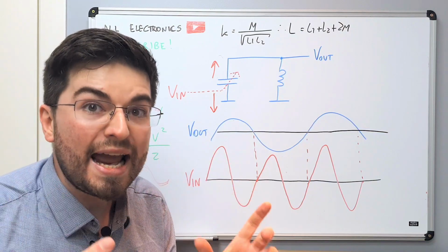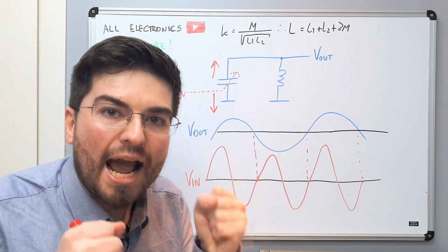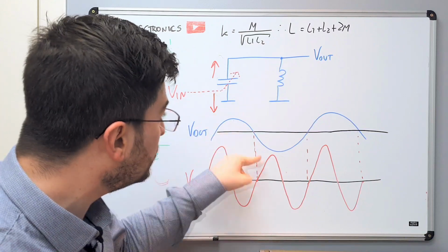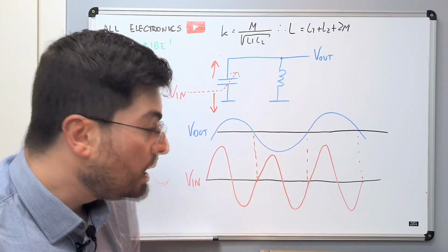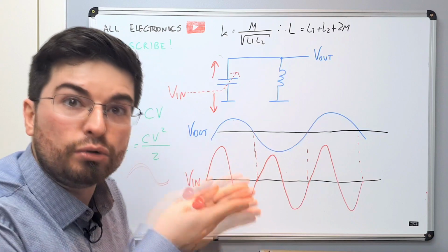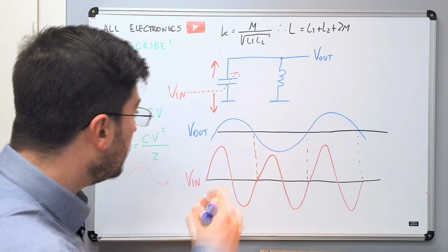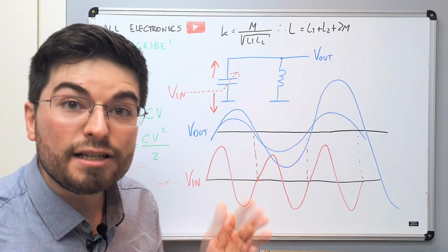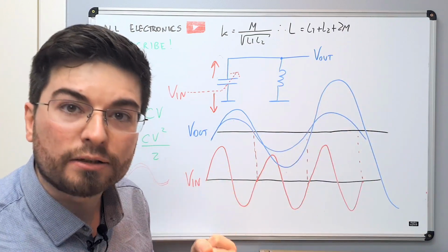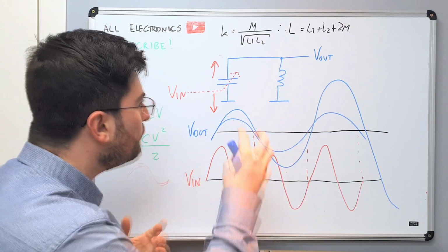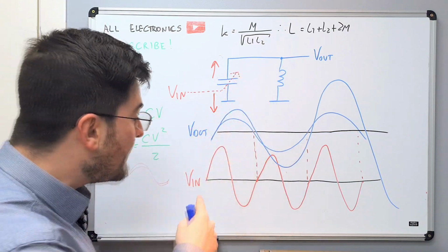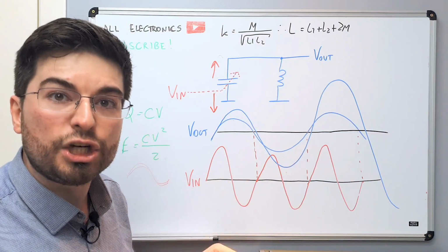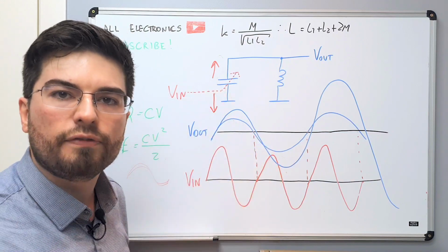So by modifying the capacitor, we injected energy into the system, and actually this voltage here would be increasing, because we are adding energy to the circuit. This voltage here would actually increase. This is parametric oscillation. We changed a parameter of the circuit or the system at double the frequency, and we induced an oscillation at the resonance frequency of the system.